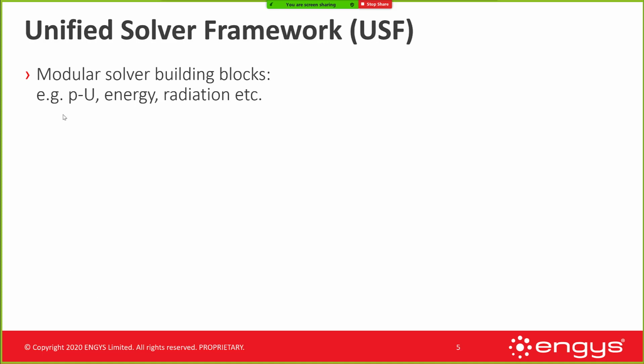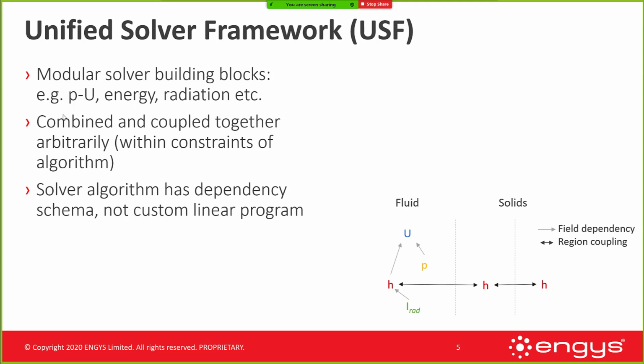At ENGYS, we've worked to develop what we're calling the Unified Solver framework. It's a modular framework in which solver building blocks, we've got momentum, we've got energy, radiation, can be combined and coupled together arbitrarily, of course within the constraints of the algorithm. The solver algorithm has dependencies between each one of these modules, and it's not necessarily a linear program like something that we'd see in the application solvers folder inside of standard OpenFOAM. We prioritize implicit coupling. So when it's possible, the implicit coupling is done between regions.